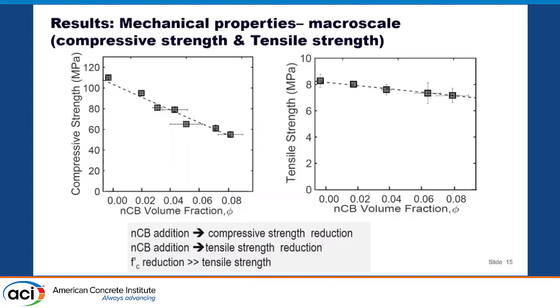Of course they are hydrophobic, so water is not really absorbed inside; they are not consumed like lightweight aggregate. But I think you still need to report on the porosity of individual nanoparticles. You still need to present the morphology, maybe TEM pictures. This would add to your study. Yeah, that's perfect. Thank you so much for the guidance.